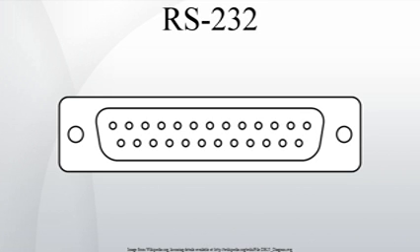For PC technology, leading manufacturers started early to replace the once common DB25M connector by the more compact and thus somewhat cheaper DE9M connector for their devices. As the pin assignments needed to be condensed, a noticeably different pin order was selected for that mechanical variant, for the serial port.